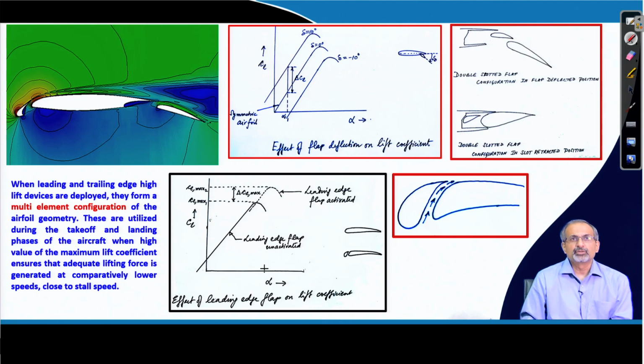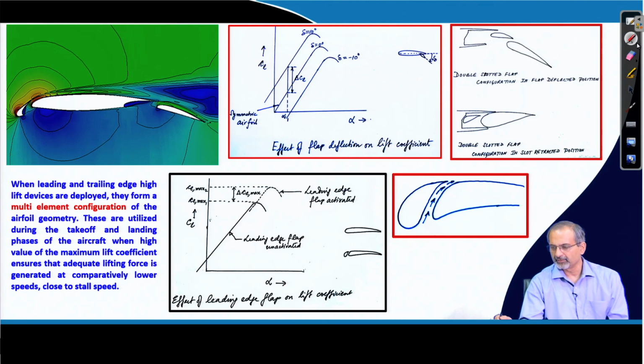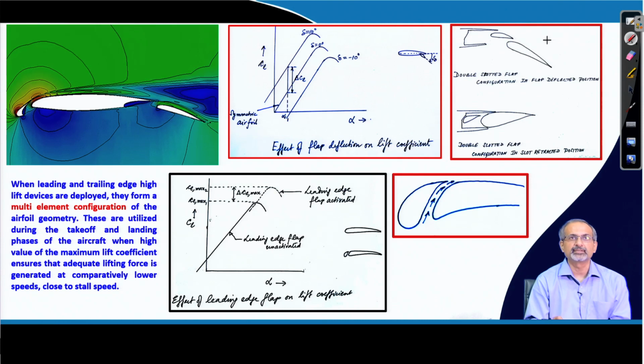Well, so we saw a single airfoil pitched up at a fairly large angle of attack and the flow has stalled. But does it mean that airfoils will never operate at fairly large angles of attack? That is not true. So, if airfoils have to operate at fairly large angles of attack under certain situations, what do we do? Do we encounter flow separation and accept the fact that they will be absolutely useless in terms of aerodynamic efficiency?